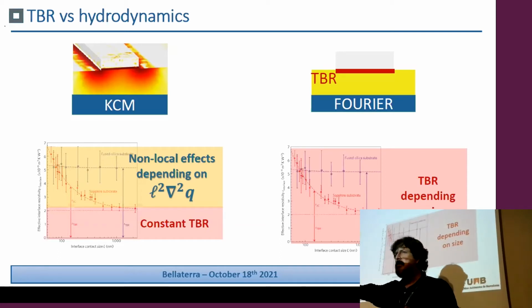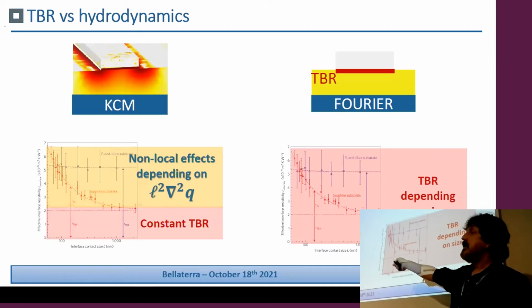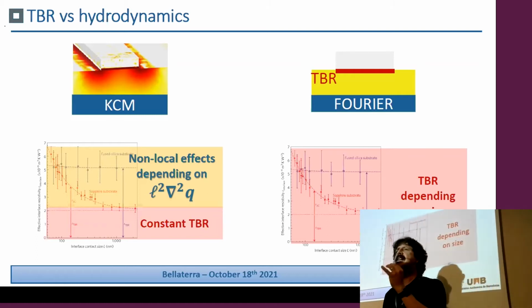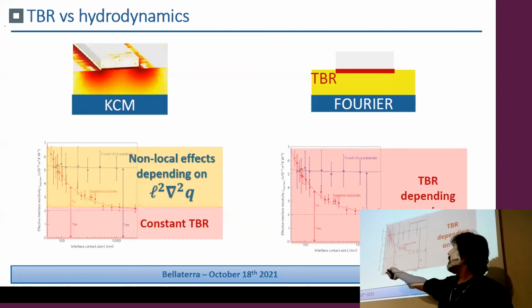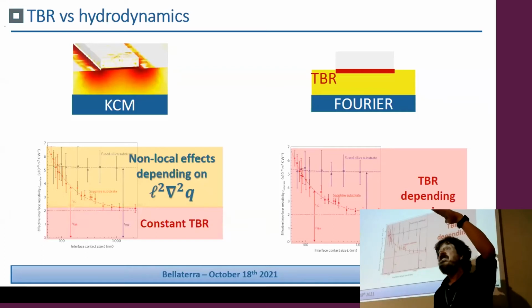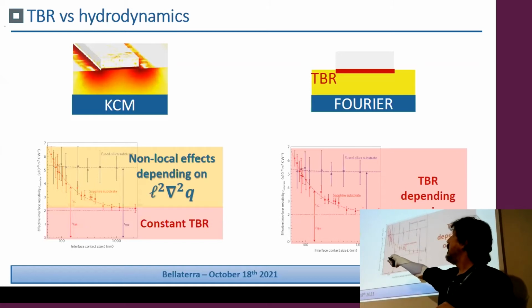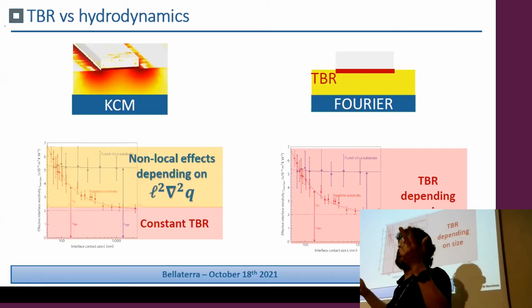Fourier limit, and the reduction of the thermal conductivity, the increase in the thermal resistivity, is just due to this Laplacian term. And what I have plotted here, you see in yellow and in red, is the effective thermal conductivity of the sample, that is the heat flux divided by the gradient of T. When you do this, you obtain something that is reduced near the structure, and when you go farther and farther, you go to Fourier, which should be the yellow one.